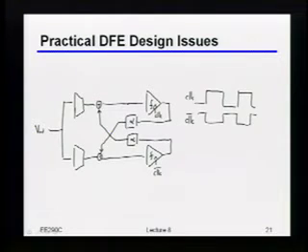Okay, so the reason I was mentioning this was, again, I may have gone to this interleaving because, as an example, I wanted to relax some of the constraints on my comparator. But notice, because I'm actually closing this first tap here, I still have the timing constraint of making the decision, going through this scaling, feeding back onto this analog node, and having it settle all before that next bit time, right? Because in this case, if I have DDR like this, each clock phase is a bit.